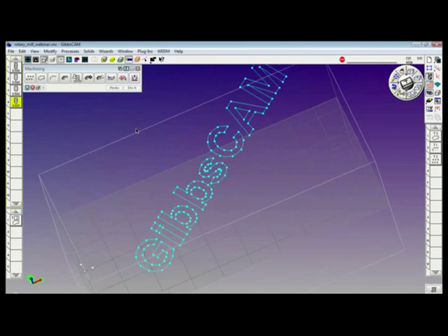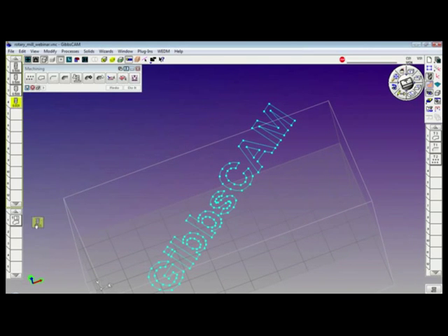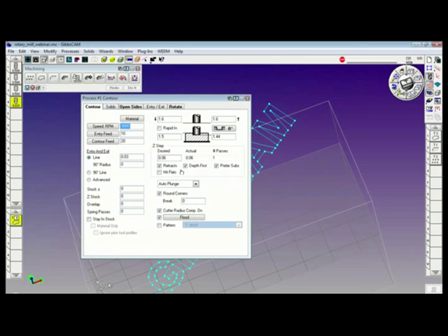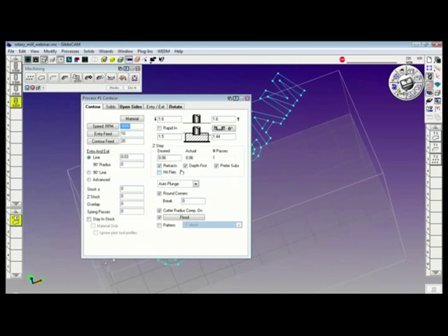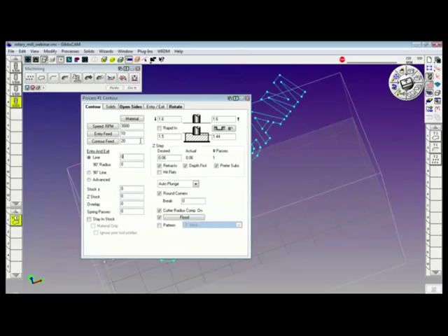Unwrap the geometry, bring the tool down, and we'll do it as a contour the first time around. Then we'll pocket it out. So contour cut, leave the same values, 0 entry moves. I'm only going to go 30 thousandths deep, or maybe 15. So 1.5 minus 0.015.